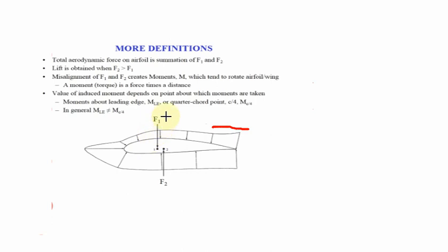So here you can see the aerofoil will be facing pressure and shear stress. The imbalance of pressure and shear stress will be creating the lift. For example, I am just marking the magnitude of upper surface forces and lower surface forces. So the imbalance of upper surface forces and lower surface forces creates the lift. Always the lower surface pressure will be higher. That is why we are feeling the lift. If the lower surface pressure is less, we cannot create the lift.